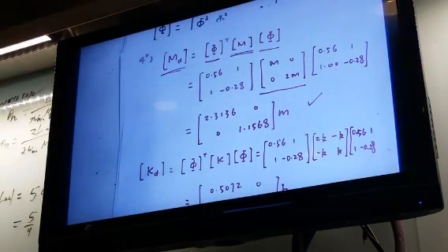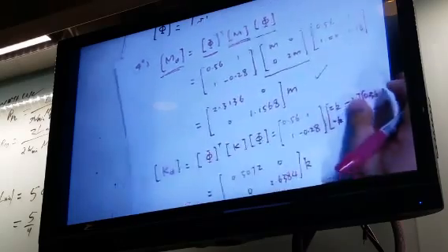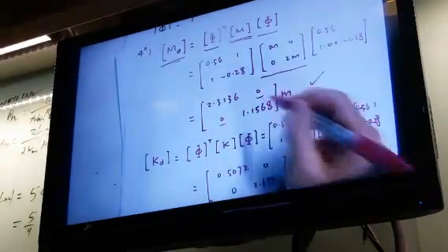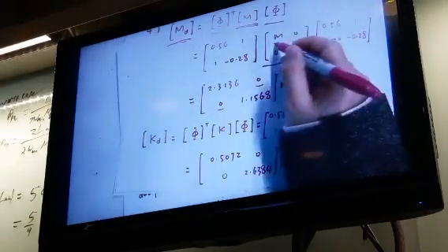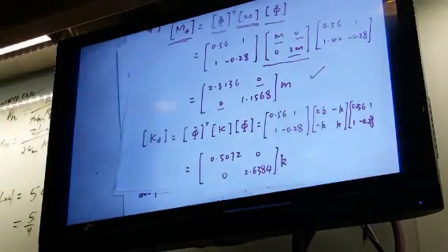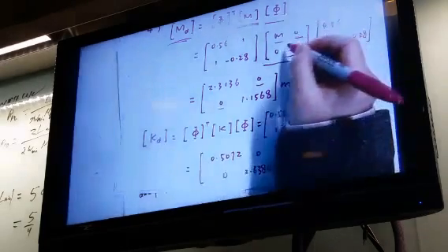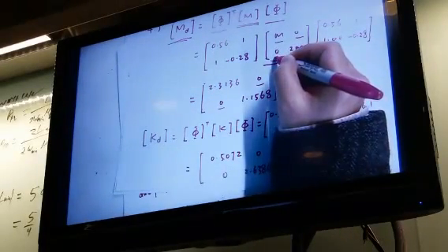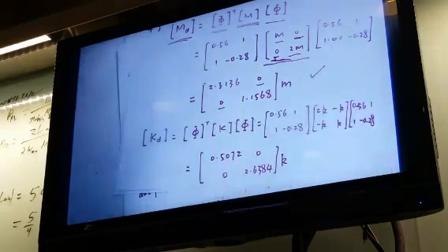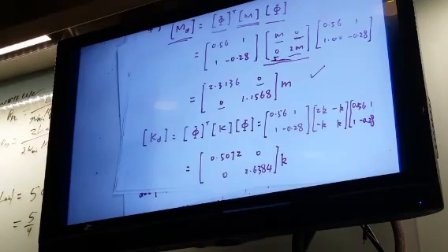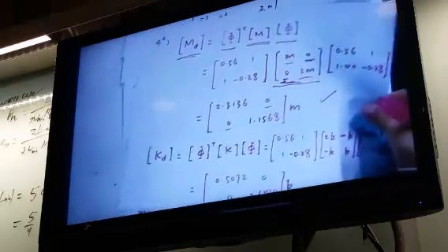in normal coordinate. The good thing about this M matrix is you have no non-zero on the non-diagonal term. Actually, initially this case is very special because you only have non-zero on the diagonal term. This is a spring mass, not a truss or beam. If you recall the mass matrix M for bar elements, you have non-zero values here, not zero. So this is zero because this is a spring mass. It's very special. So this is how we transform the mass matrix.